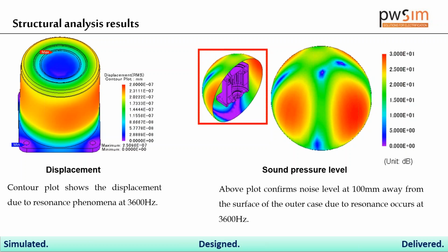In thermal, what you do is that you assign the thermal properties of the material, you create your thermal circuit, and you couple the losses that you obtained from the 3D magnetic analysis into the 3D thermal analysis.